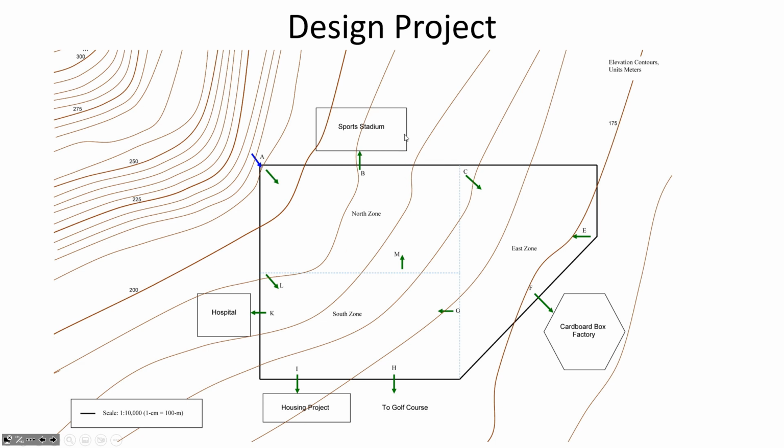So part of your project is trying to identify what's the most optimum pathway for the water pipelines to take. Part of your design project is trying to figure out how big the pipe diameters should be. Should you put in a 100 millimeter pipe between A and B? A 750 millimeter pipe between A and B? Well, a 750 millimeter pipe is not likely to have very much head loss, and so it would be really good at ensuring that you have high water pressure at B. But that big diameter pipe is also very costly and maybe not necessary.